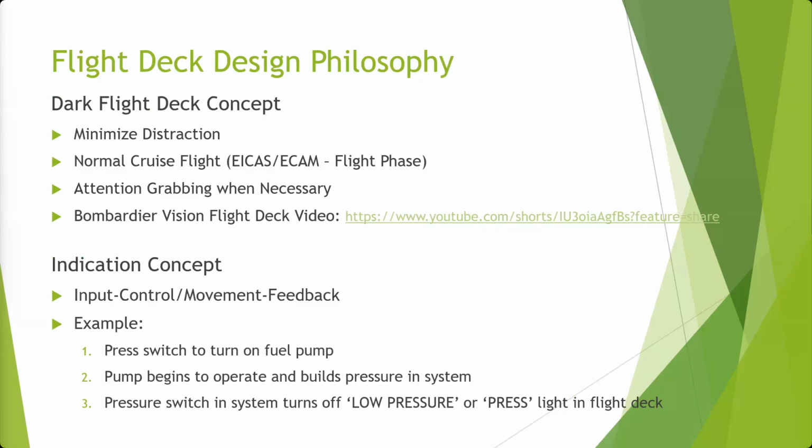When we get to flight controls on the ICAS indication, most ICAS systems have a flight control position indicator. You can look at where every flight control is on the aircraft relative to its neutral position.